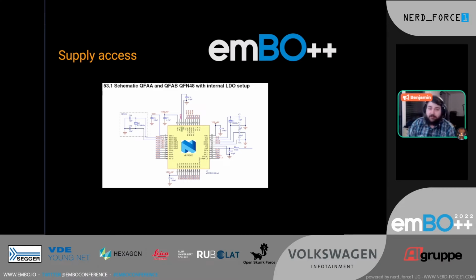And once you look at this, it might seem a bit overwhelming, but you can easily remove candidates that can't possibly be your target, because you're looking for something that connects to an internal voltage line and that uses an external decoupling capacitor to stabilize this voltage. So you can instantly remove anything that has anything else connected besides ground and a capacitor.